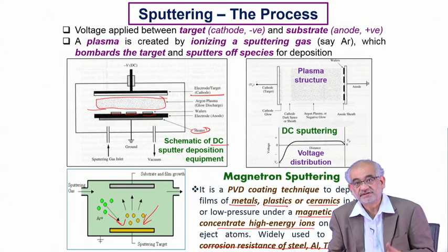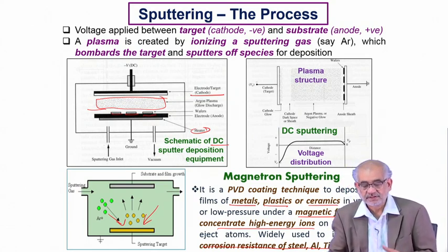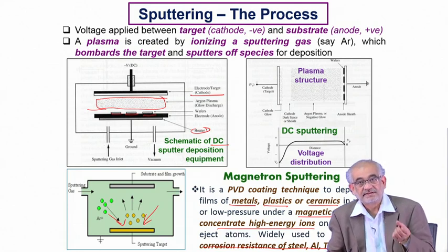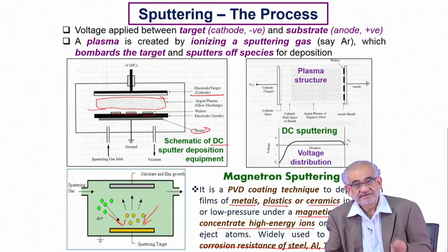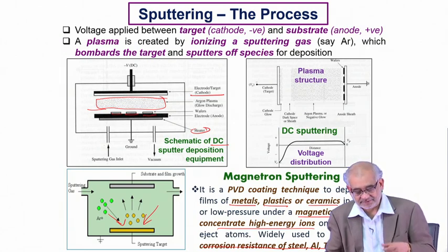You can create a cathodic or an anodic layer to prevent corrosion and oxidation, but very thin. And the other advantage is that you're not exposing to any aqueous bath, you're not subjecting to any high temperature, you're doing it more or less at room temperature, and most importantly you are able to maintain a very thin, precise layer.